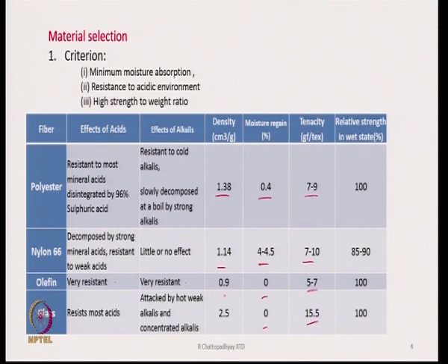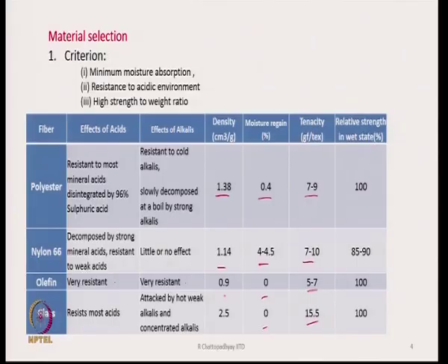Because the fabric is going to be used in the swimming pool, we need to know that the strength should not decline if it is wet. Though the fabric will be completely covered by some chemicals, there could be occasions where it may be exposed to water, and the water can penetrate and weaken the fibers of the fabric, and the tenacity may go down.